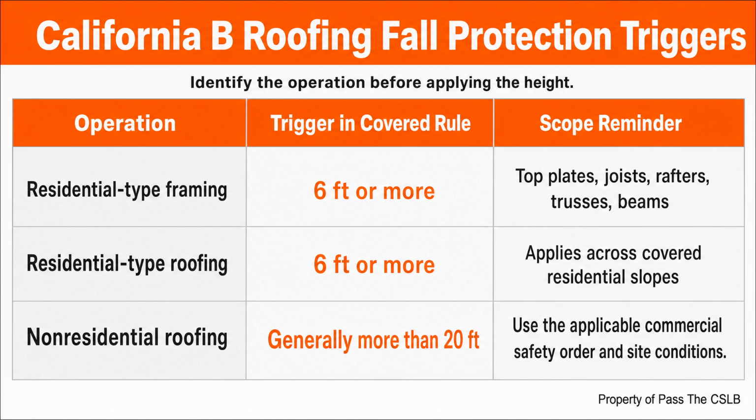For asphalt shingles, I check the 2 and 12 absolute minimum and the double underlayment range below 4 and 12. For wood shingles or shakes, I remember the 3 and 12 minimum covered here. Fourth, I inspect the framing interfaces, ridge board thickness and depth, rafter alignment, permitted offset, ties, and hip or valley member dimensions. Fifth, I trace water from the high point to the discharge point.